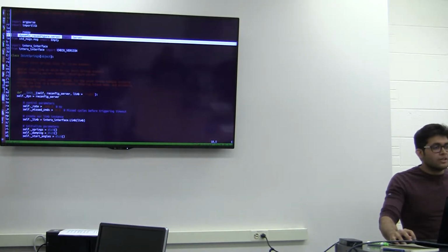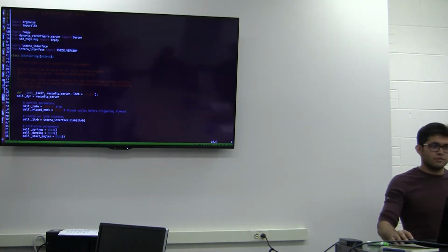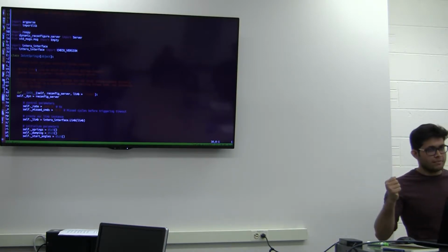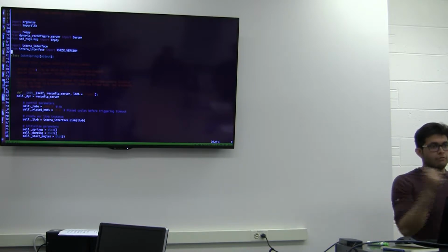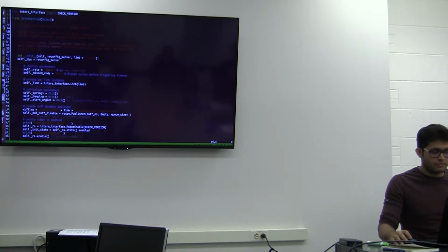To be fair, I don't know deep inside what this server is doing. All I know, it measures the position difference and moves to that position. So if you want, you can read more about it. What it does is basically, where's my current position, where's my home position, and how far I am. It just calculates what torque it requires to move from one part to another and executes them. So you always have to run this. It always runs because you call it here from the server.